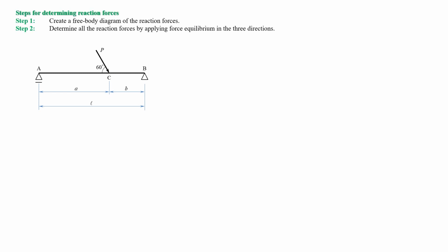Steps for determining reaction forces. Step 1. Create a free body diagram of the reaction forces. Step 2. Determine all the reaction forces by applying force equilibrium in the 3 directions.